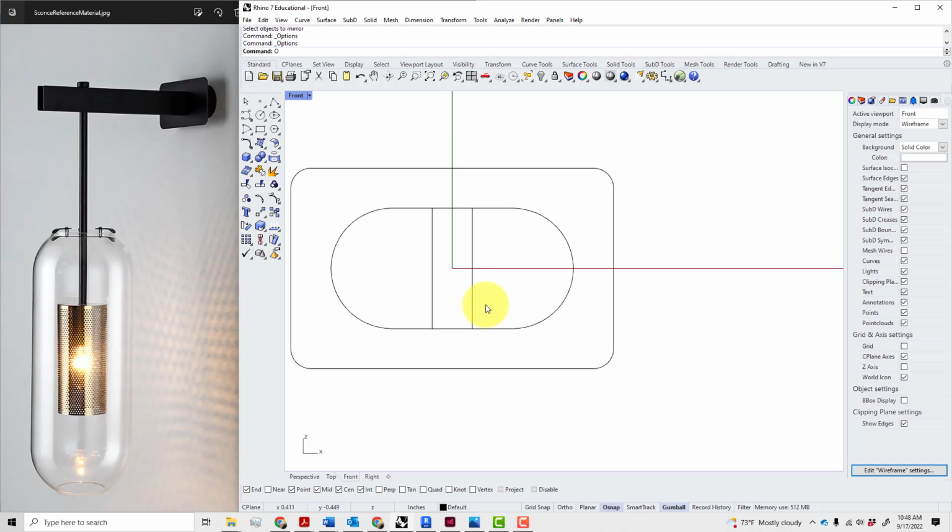Okay, so we're now going to do some more offsetting. I'm going to assume that this steel is 16 gauge, so we're going to go 16th of an inch. 16 gauge just happens to be a 16th of an inch. Don't think that 12 gauge is a 12th of an inch. That's not how it works. All right, so we're setting that up. So we have the main structure. I think we have enough now.